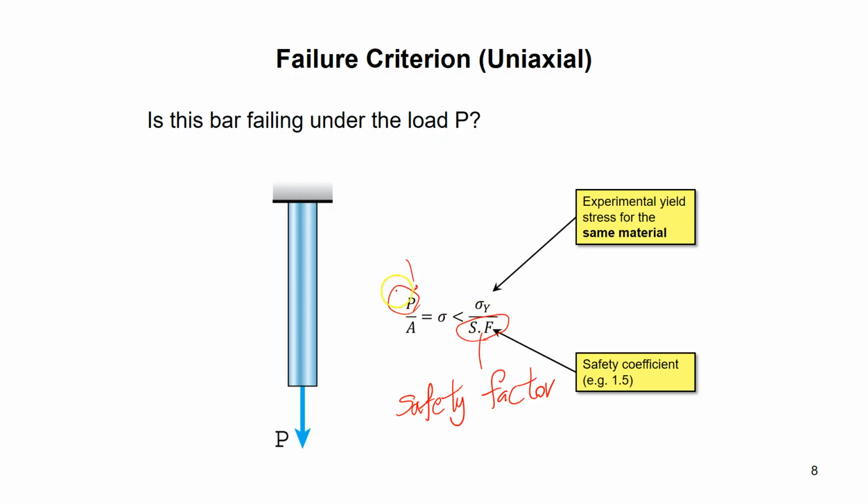And the more uncertain you are, the bigger safety factor you would use. It's quite interesting that for elevators, you are using a safety factor of 10 to 12. In other words, the rope of the elevator is so thick that you are only using 8 to 10% of its strength for 10 people, or 5 people, or whatever number you write on the door of the elevator. Because you don't want to take chances. You want to be extremely conservative in the design of those.